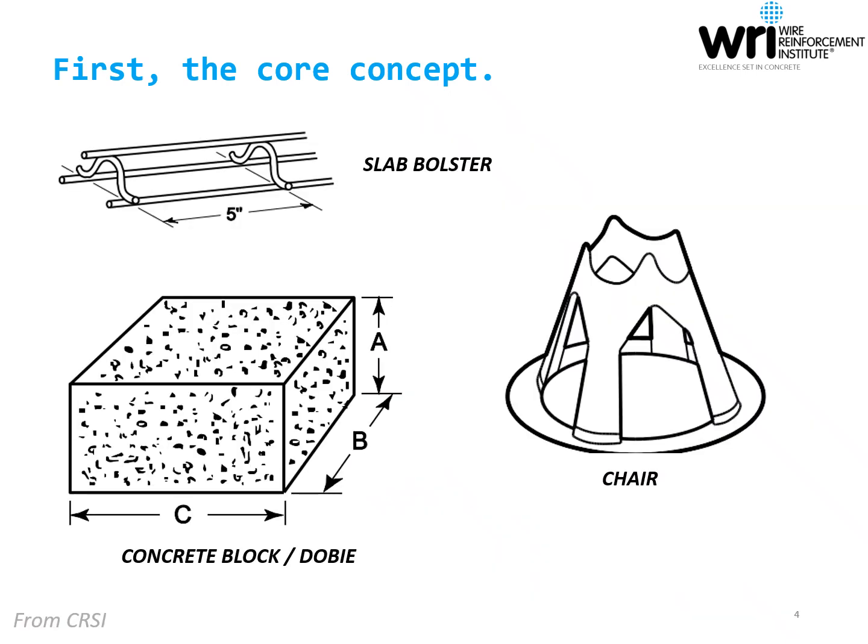A few examples of reinforcement support types are illustrated here, taken directly from CRSI's RB 4.1 standard. The contractor's selection of appropriate support strategy is a function of numerous project-specific considerations that can include the stiffness of the substrate upon which the support rests, to the weight and flexibility of the supported reinforcement itself, to the type and duration of construction loading applied to the reinforcement during installation and the subsequent concreting operation.